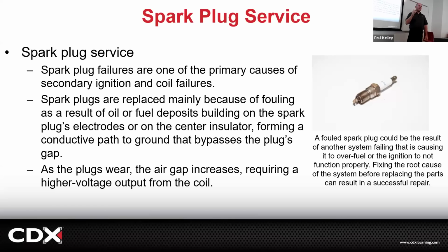So when we're looking at that, that's some of the reasons we're replacing them. Now, does it start to make sense why if we do the iridium coating, that's very, very hard, platinum or something, that's going to decrease the amount of surface wear, which means that gap should stay good a lot longer. And that's why we don't need to replace them much. But if the spark plug is fouled because the coil failed, it doesn't really matter that it was iridium coated and the gap is good. We need to remove that conductive path without scraping off the iridium. That's probably not going to work. We're going to put a new spark plug in there. You follow the logic there? So that's what you've got to be thinking about.